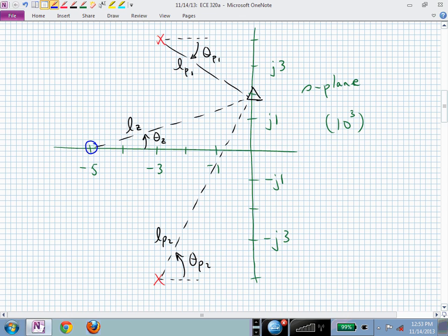That's pretty fast, isn't it? Because now tau is something underneath t that produces 3,000 in the numerator. So it's 1 over 3,000. That's our tau, and we need 5 of those. 5 over 3,000. We're not having to wait very long before we get to our sinusoidal steady state, are we? 5 over 3,000 is 1 over 600 seconds. And then we're there. We're in the sinusoidal steady state. Is that making sense? Yes.